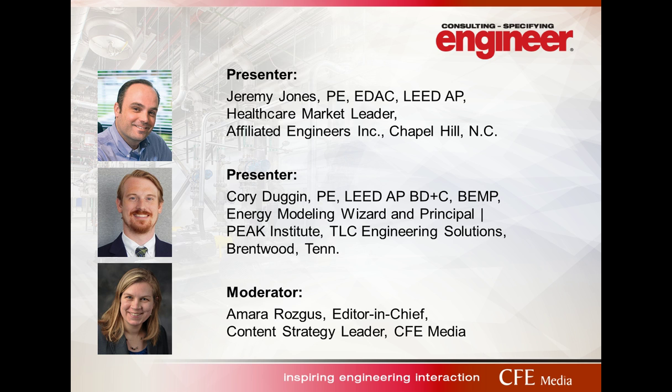And in an ICU, there's a lot of equipment in there keeping that patient alive. So you really do need to check your loads to make sure what the maximum truly ought to be, because I have seen it be significantly higher than the code minimum. If you have a patient room or any rooms with significant glass exposure because they want nice views, that's another thing that can drive the load up. So I would not say that there's not a lot of variation in a VAV system. I have seen the opposite.